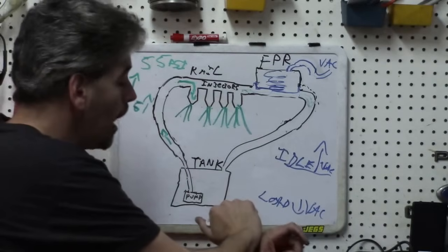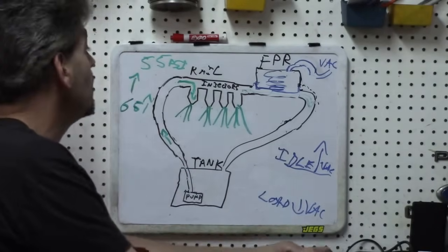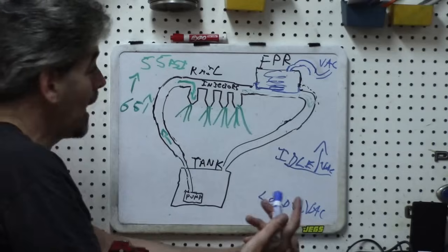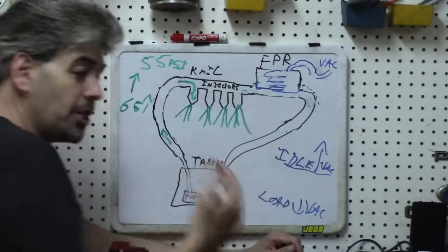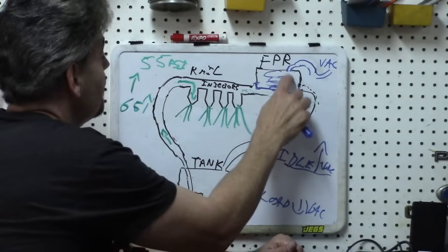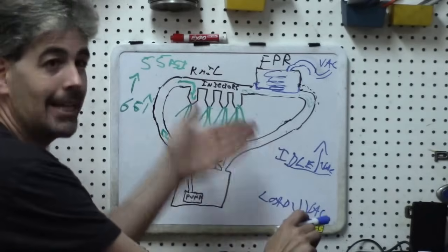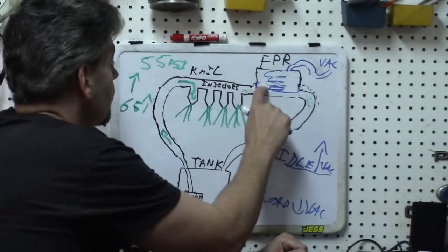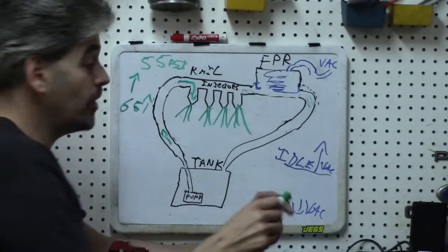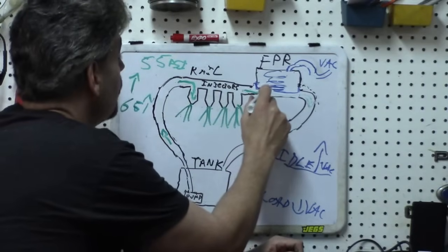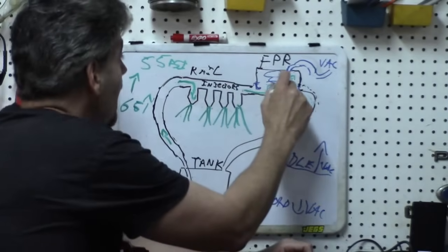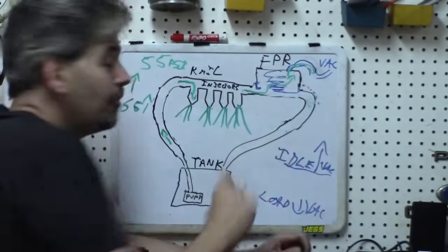All right, and one other thing to keep in mind that will also help you with your fuel pressure regulator diagnosis, and that is, at least every time that I've seen it, if you have a rich condition in the vehicle and you find that when you apply vacuum to your fuel pressure regulator, you do not get any response, then almost certainly what's happened is this diaphragm has become compromised. And very often what you will find is that a lot of the fuel flow will actually go into the fuel pressure regulator itself, and as a matter of fact, into the vacuum line itself.